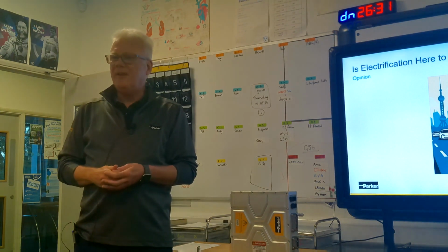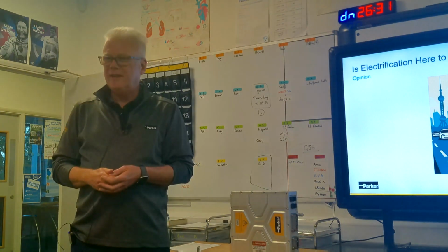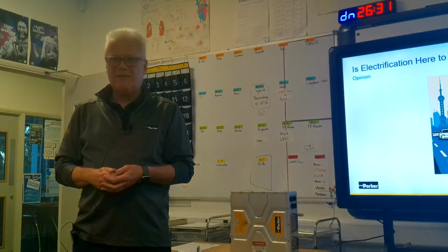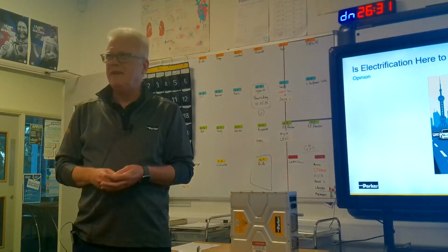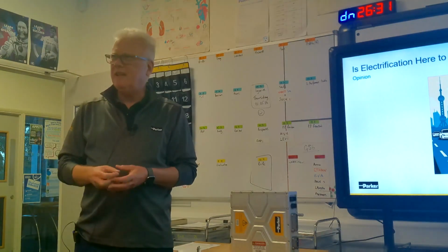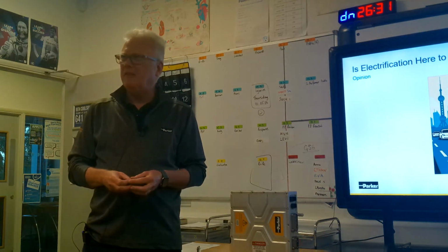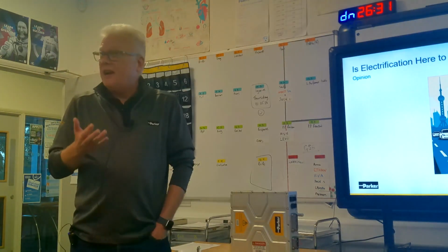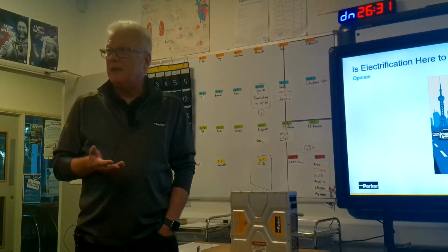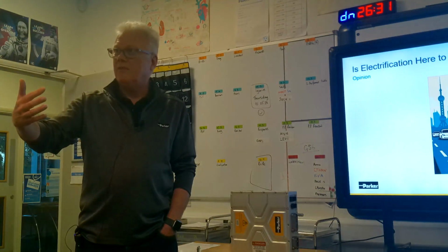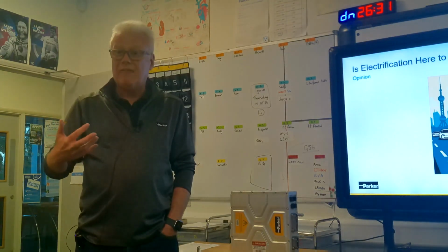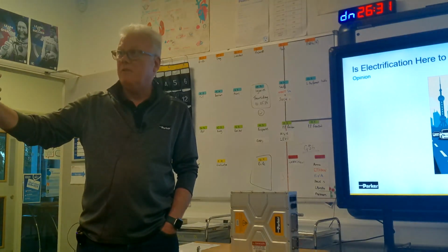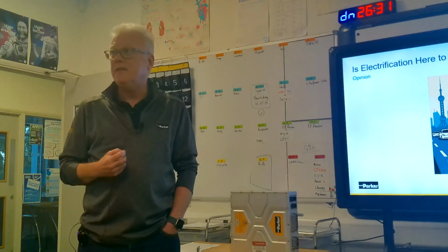The challenge there is failure rates. I was quite surprised to hear that the failure rate of gas turbines, the FIT rate, is like 10 to the minus 10. So next time you're in a jet plane, think about that. The chances of that thing going wrong are practically 0. Whereas I can't say that for an electric motor. They just can't reach that sort of level, which is why there's this interest in making fault-tolerant motors and inverters, because then we could push the failure rates up to the sort of thing that aerospace needs.